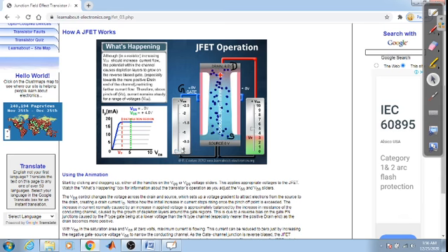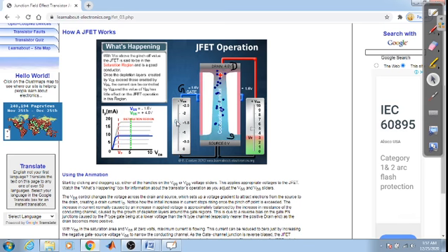If we give negative voltage, 0, minus 0.5, minus 1, minus 1.5, minus 2, and go on increasing the negative voltage, just look over here: at 0 voltage this is the current, it is conducting. If we go on increasing the negative voltage, see the current conduction is decreasing, because the channel is getting reduced, the channel width is reduced.